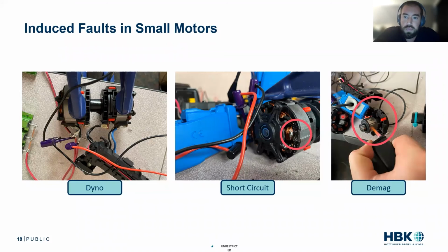And then in another example, I bought a bunch of power drills. I took my lighter to the rotor. I got it extremely hot and pulsed a ton of current at it and demagnetized it. So I have these two examples. I don't have a bearing current example. That one is harder to replicate on your own, especially in this machine. So this is why I had a lighter.